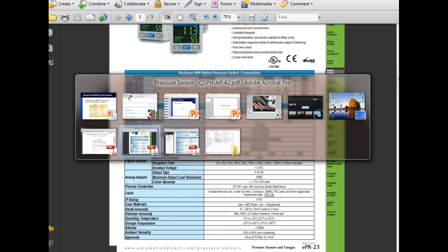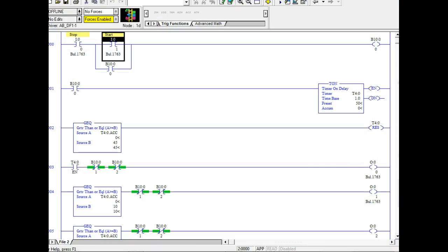Now what we do is, and this is what we talked about, we have these bit registers, right? We got B3. Some PLCs have a B3 and a B10. If your PLC has a B10 register, that means you got 512 of what we refer to as internal coils. In motor controls, we call them control relays. So in motor controls, we have 3 categories of relays. We have control relays, and what that means is the contacts never leave the control circuit. All the contacts are within the control circuit.